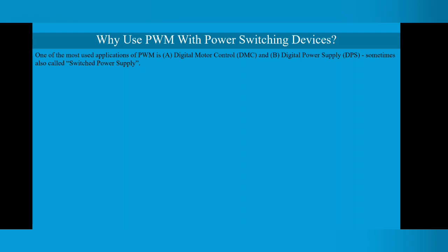They also use pulse width modulation because in a UPS we have a DC waveform and we want to get a 50 hertz or 60 hertz sine wave output signal. In this case, we use the pulse width modulation scheme to get the desired output magnitude and desired frequency.